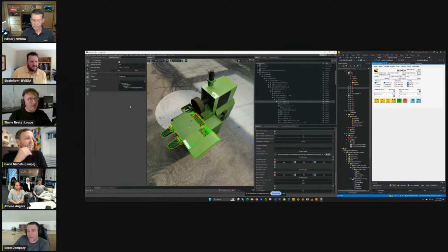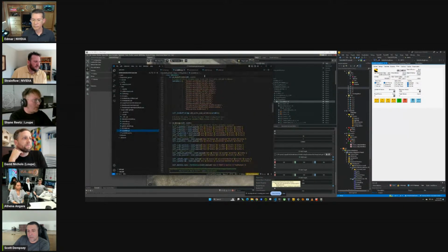This one uses a protocol called ADS that is something TwinCat offers. On the B&R side, we use WebSockets and a library that we wrote for B&R controllers. So a little different, but essentially you get the same user experience as a developer, and as to how you can request and then use data from the PLC. And it can actually go both ways. So we can write data to the PLC, and the PLC writes data back to us.